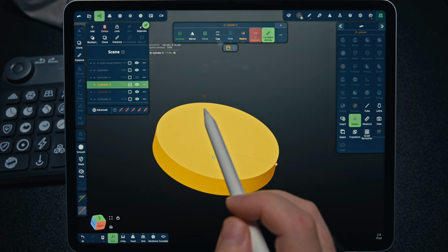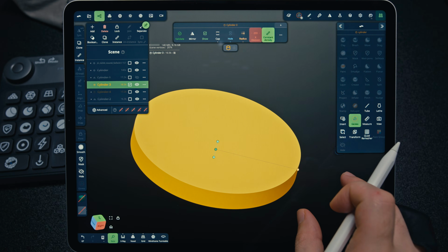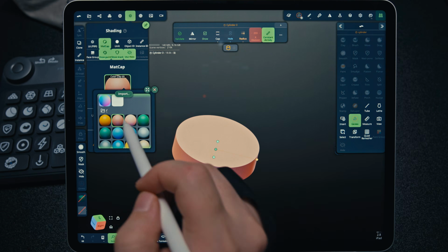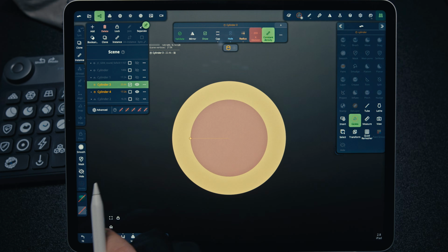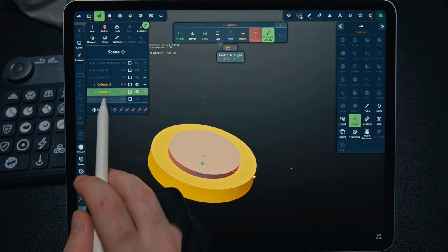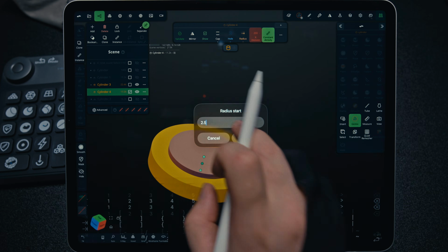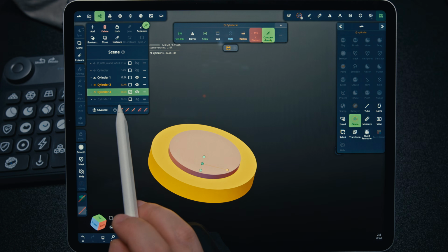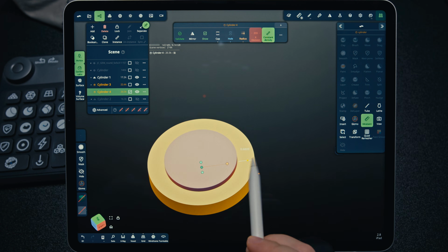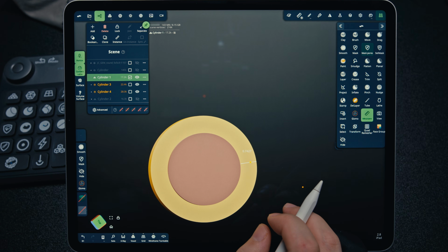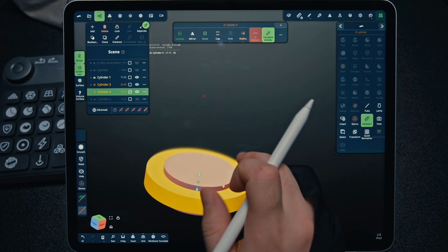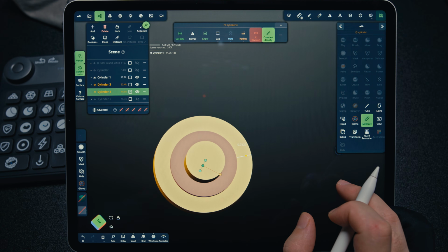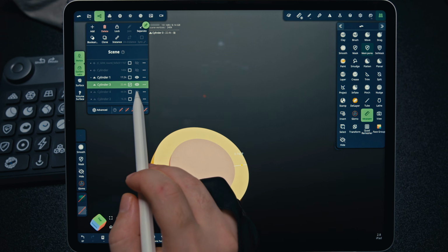So, keeping in mind the 0.8mm rule, I calculate the dimensions of the cylinders with simple math. If the cylinder is 5mm and we want to leave a 0.8mm thickness, then 5 minus 0.8 times 2 equals 3.4mm. I won't talk through all the math and we will just speed up the video.